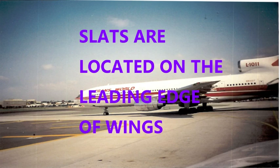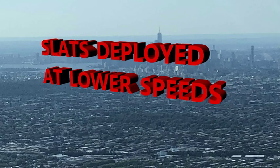So why are they there? We have the flaps on the trailing edge, and then we have slats on the leading edge. It's a similar situation where it's allowing those wings to have a greater surface area, which allows a higher angle of attack when the plane needs a really short takeoff or also in landing. Pilots are typically going to deploy the slats when they're flying at lower speeds. Okay, so that's another condition.